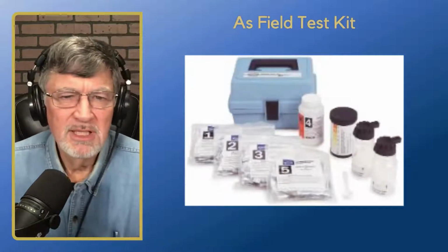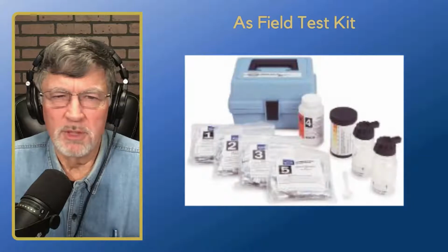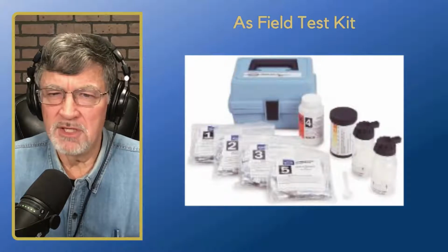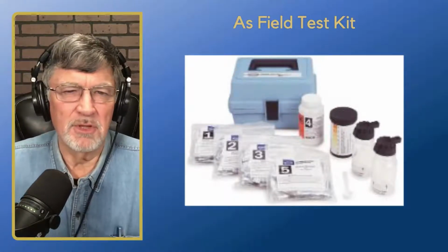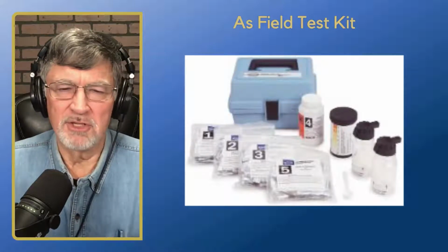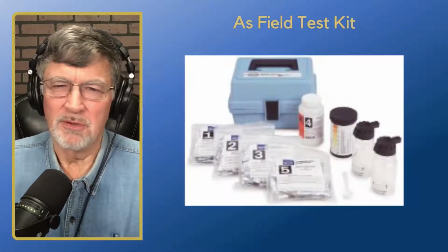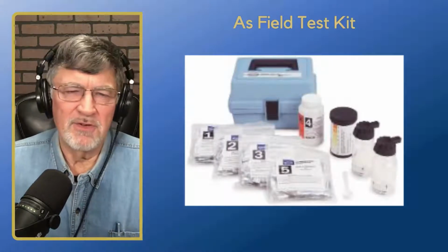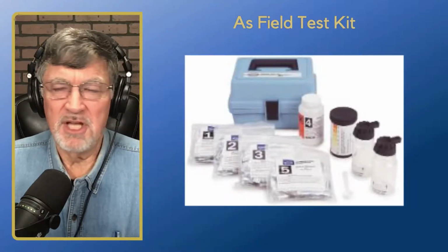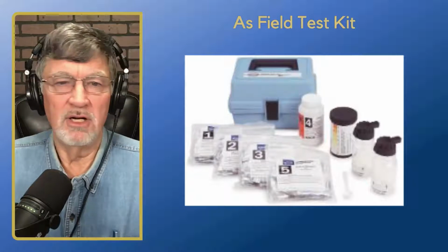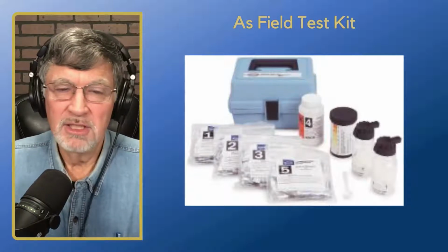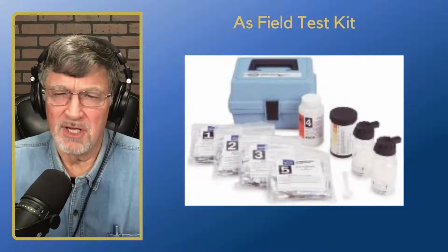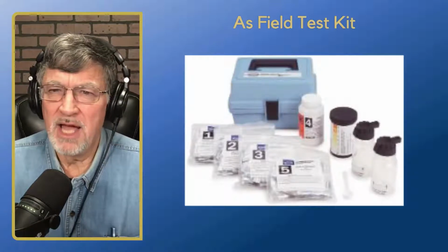Also, I just want to mention, generally these samples we're going to pack up, put in laboratory-approved containers and ship off to the lab, but there are a number of field test kits out there. Here's an arsenic field test kit, but there are a lot of them available. Some of these will actually plug into your iPhone so you can record the readings and GPS the location. So you have some pretty fancy and sophisticated tools for testing on site to give you an indication of what's going on as you go along, so you don't have to wait for laboratory turnaround times. These can be good, and the accuracy of these things is getting pretty darn good. It's still not laboratory quality.